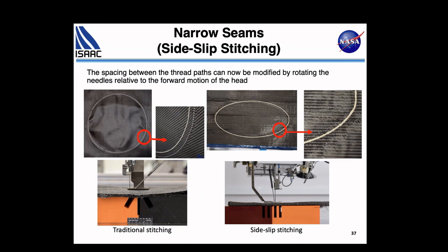The other thing that we looked at was trying to do stitching better in a more compact manner. That big cavity you saw in the earlier chart underneath there allows the fabric to sag, which means you have to stretch it really tight, or you have to put a layer of fiberglass underneath to keep it from sagging. Well, we found a way to put that material over a very small cavity by rotating the head. And instead of stitching with a 1/4 inch wide part, we can stitch in just millimeters wide. And so we have a much smaller cavity, which means you've got a much tighter seam.